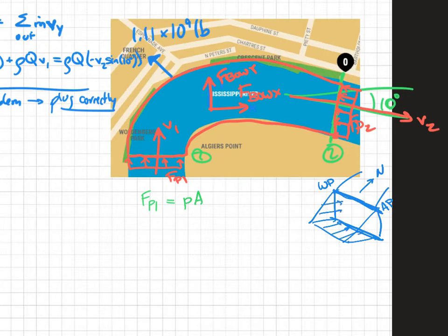I don't know how to draw that for this whole thing, but you've got the idea. So remember, how do we deal with pressure prisms? We want the average pressure and multiply it by the whole area. How do we get the average pressure? You can think about it as the centroid, or because it's a rectangular face, you just think it's halfway down, which gives you your average place.